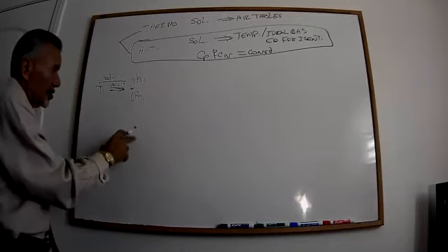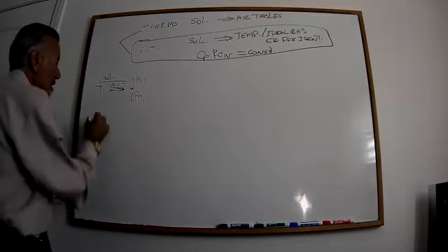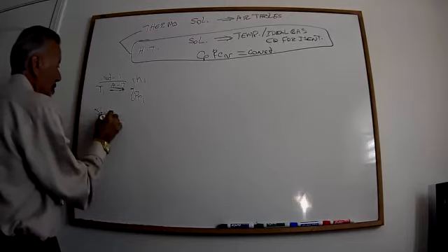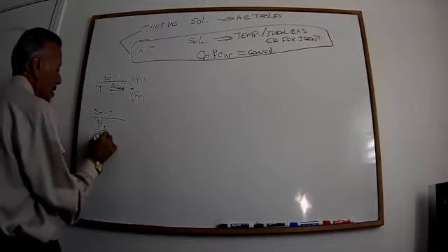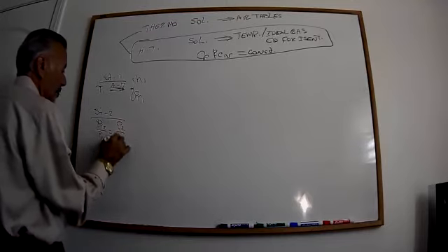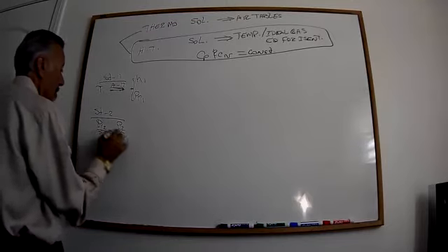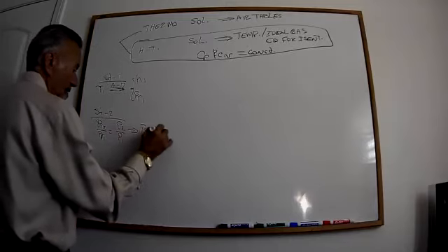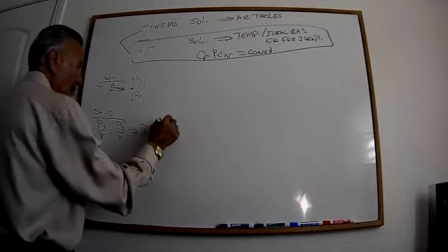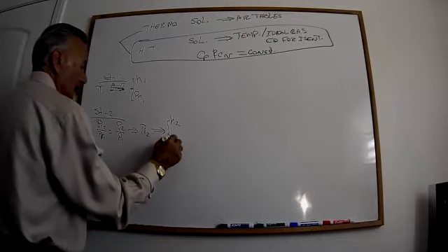Now we have a pressure ratio, we find PR1. At state 2, we write PR2 over PR1 is P2 over P1, and that's how we find PR2. Based on that, we go to the table, we find H2 and T2.